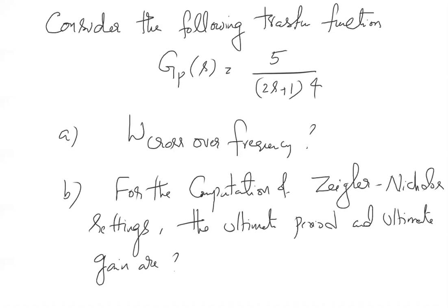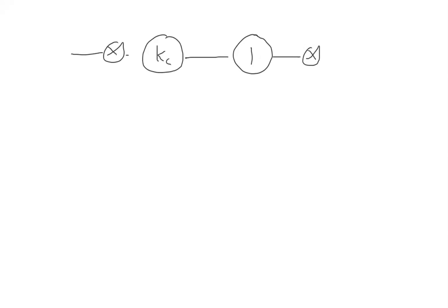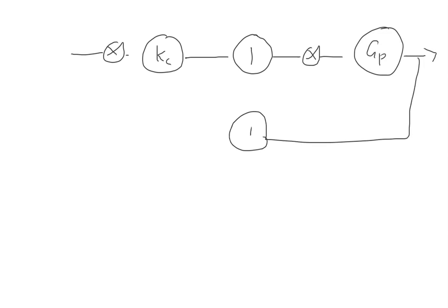So here, if you remember, the transfer function is only given for the process. How do you find the control loop? First, you have to frame the control loop. So it should be proportional control. Always you do calculations for the proportional control. Since valve and measurements are not given, you can take them as 1. This is the control. So you do all this ultimate gain and stability calculations for the proportional controller only. Now you solve what is crossover frequency.